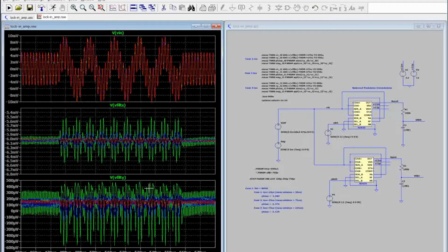And depending on the averaging effect, you'll see that the value will be different in each of the 3 cases. The case where you have the longest time constant, you're going to get the best filtering at the cost of a longer settling time. So the green curve shows the shortest time constant, and the red curve the longest time constant for both these curves. If you look at the data next, I'll plot that and show you here.